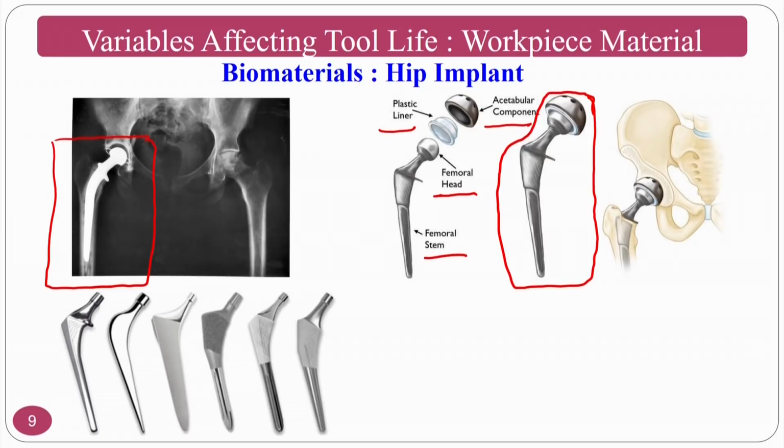But if you see like the previous video where the firing is there and all those things, there will be a temperature effect on the workpiece. Normally if you see the femoral stem, this is machined and different stems are there. So the basic stem, if you see the first one, is basically machined by the milling process. If the milling process is like the previous one where fiery red chips are going, then the metallurgical aspects of this will go bad. So I don't want that.